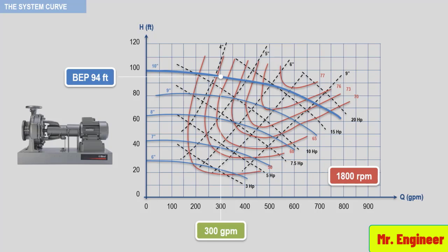65%. So, if this pump were bought off the shelf from local distributor stock, it would probably be a 3x4x12 model end section centrifugal back pull-out pump, with the impeller machined to about 10 inches before installing the pump into the system. And that's the way it is done for a new installation.